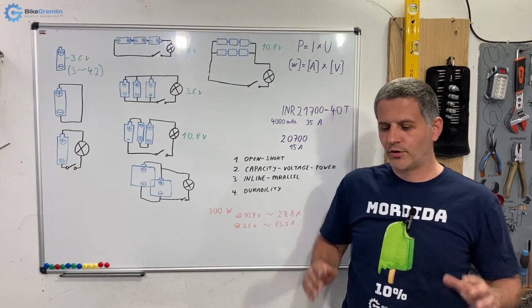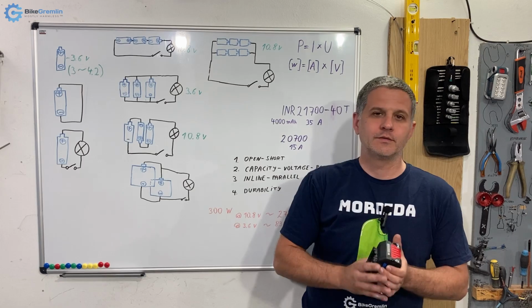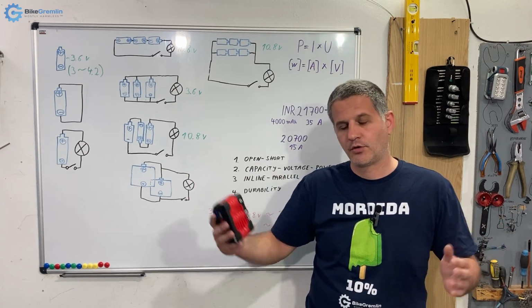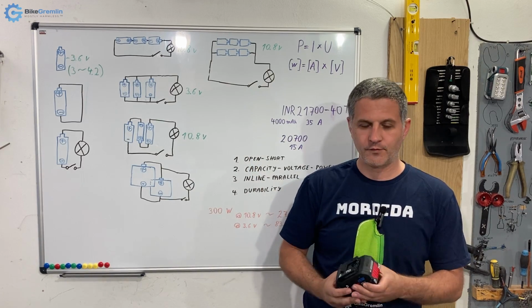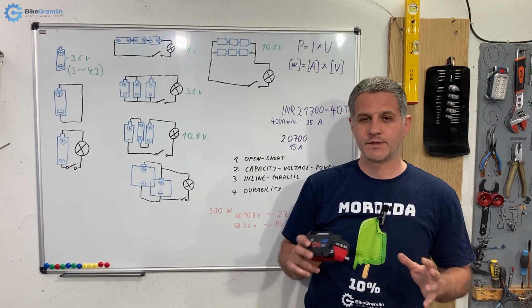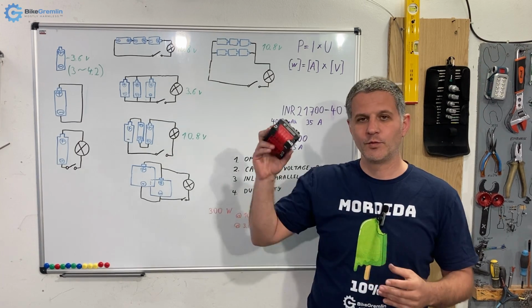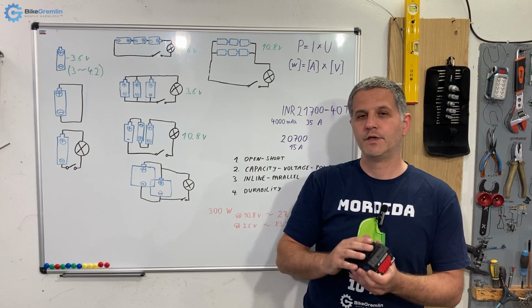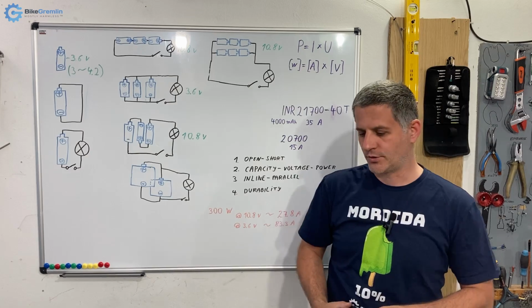If you want to store your batteries for a longer period, it's best to store them at room temperature or a bit cooler, but not below freezing and not hot, like 30 degrees Celsius and so on. And it's best for the lithium-ion batteries and similar to be left at about 50% capacity. So don't charge them to 100% if you wish to store them for longer. They will degrade less if they are not 100% charged when you store them.